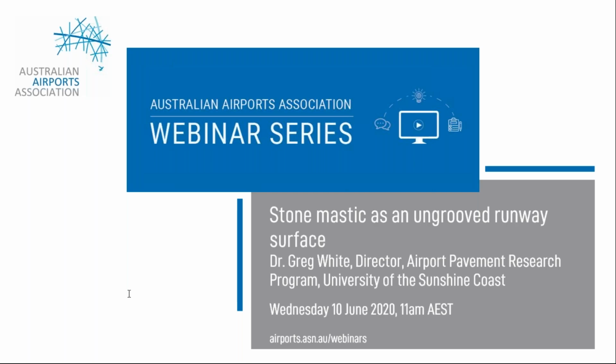If anything, the extra bitumen also increases the binder film thickness, the thickness of the binder that's around every stone, and that extra thickness should reduce the effects of any aging or oxidation over time. It's probably not the most scientific of answers, but I don't think that's going to be noticeably different from our current mixtures in terms of stiffening up over time.